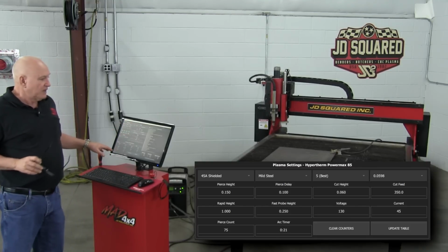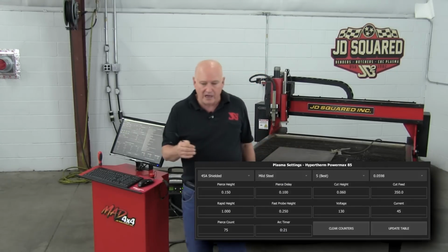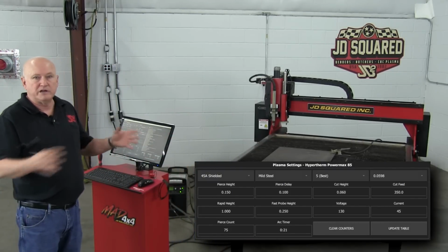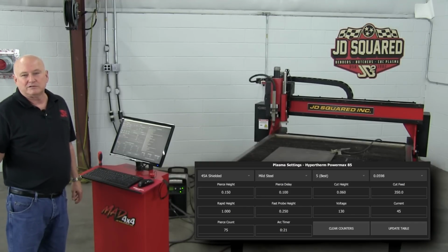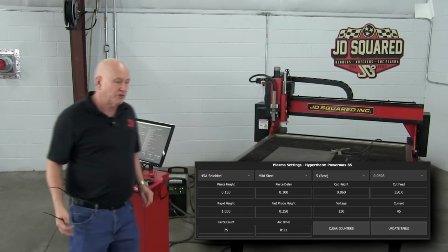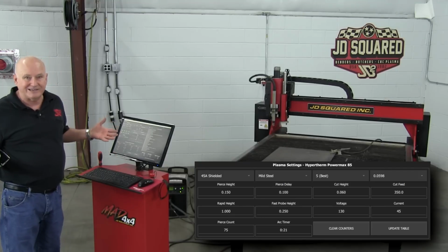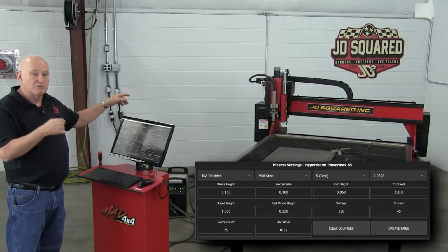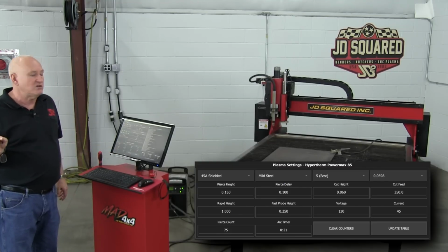So what we're doing is, let's say you're loading up this beautiful piece of artwork, you got days in this bad boy, and you're looking and go, man, that thing's got, you know, 300-400 pierces in it. I mean, this is a 30-minute cut. And you look down at your pierce counter and it says, hey, you've already pierced 240 pierces. Well, it's pretty much telling you better change the consumables. Well, to track that, we built it into the machine. Well, now you're not guessing anymore. So right now, for instance, it's telling us that this consumable group that's in our machine currently has a pierce count of 27 and arc on time of 18 seconds.